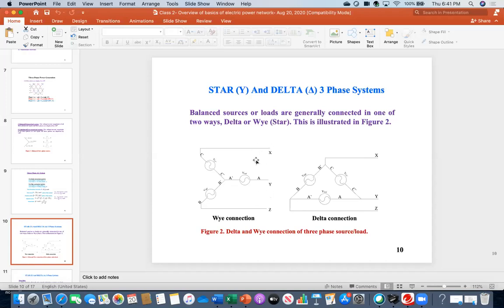If any unbalance happens, this means that, as I told you, there will be some circulating current flowing. That time, that additional current will start flowing through the neutral line, and then it depends on the magnitude. Neutral is typically designed to maintain a certain amount of current. You cannot overload it, or the neutral will be disconnected because it will be burnt out. But during the unbalanced situation, in this configuration, additional current starts flowing through the neutral.